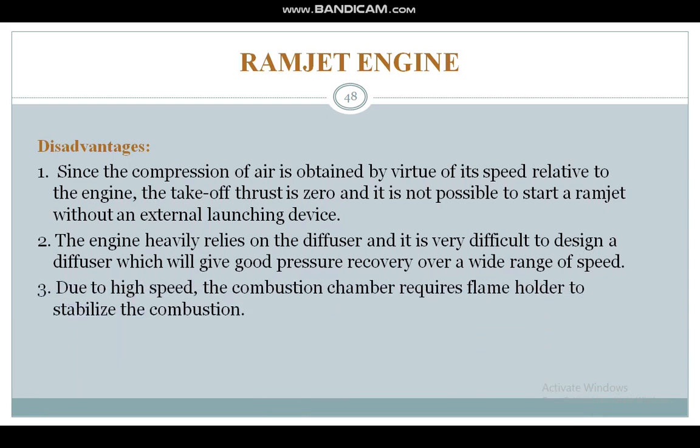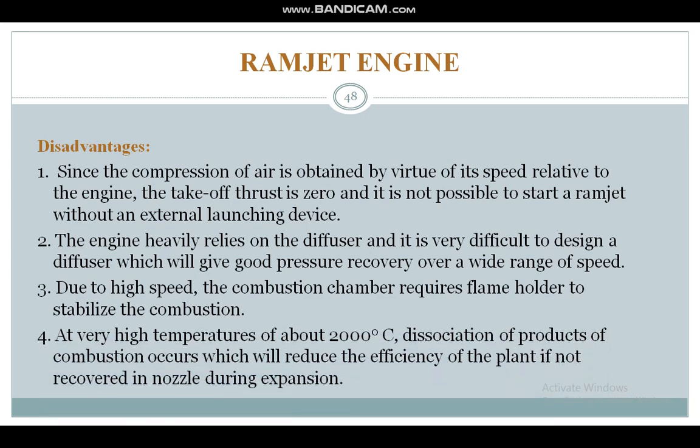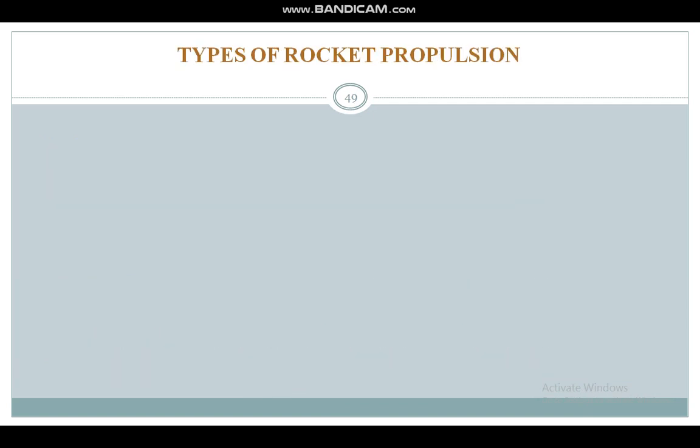Due to high speed, the combustion chamber requires a flame holder to stabilize the combustion. At very high temperature, at about 2000 degrees Celsius, dissociation of the products of combustion occurs, which will reduce the efficiency of the plant if not recovered in the nozzle during expansion.